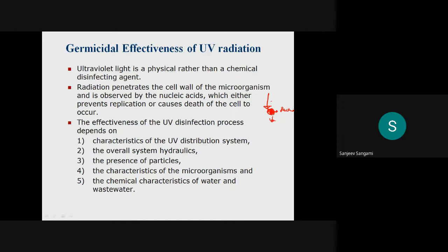Then the effectiveness of UV disinfection depends on the characteristics of the UV distribution system, how exactly you are supplying the UV light, and the overall system hydraulics. What pressure you are maintaining, what head, what distance? A thickness of 15 centimeters is required; only that much it will penetrate.